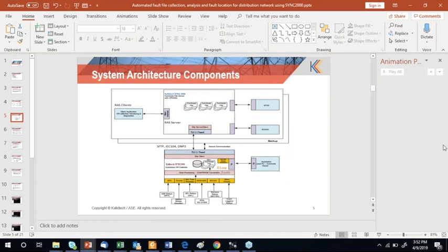And this is based upon the substation level. This file will be available in the event file, and it is pushed to the central system based upon the events which we collect. But other protocols like SPA and Courier come from the relay in a totally different format. So the user needs to sit and map the event number to the actual description and what the change is, and once that is done, it enables an automatic description scenario to be exposed to the center.